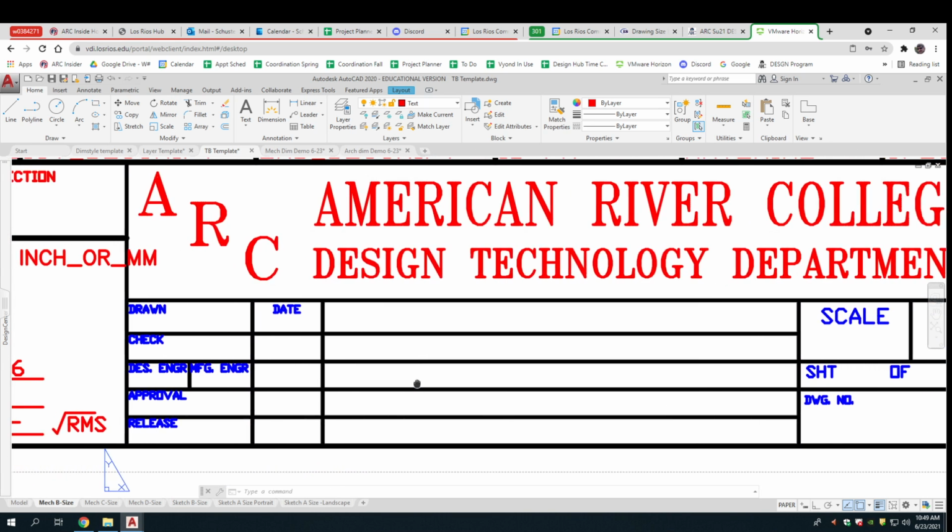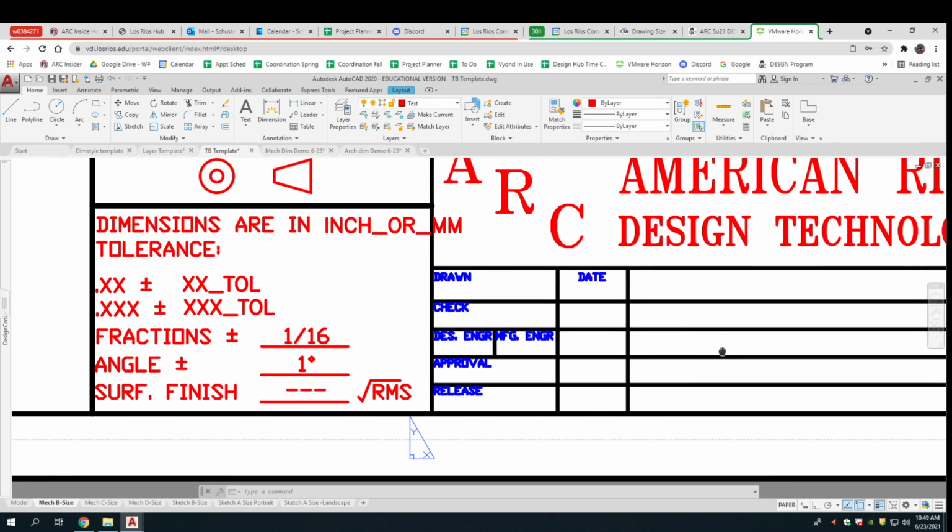And then somehow, some way, mechanical ones always tell you about tolerances. There's a standard in mechanical that says you must clearly identify the full acceptance criteria of all dimensions. Well, just imagine if you had to write that on every dimension. So this is where we have a little code. If it's written to 2 decimal places, I'll have a certain tolerance. And if it's 3 decimal places, I'll have another tolerance.